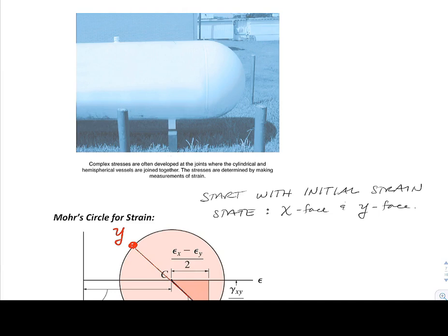And so here's a pressure vessel picture, and really what happens is you end up with calculations that are very challenging to do with a state of stress example. Obviously, we use St. Venant's principle in all our calculations, so we stay away from the area of applied loads and connections. And so to be able to help you calculate states of stress that would be in areas close to supports, close to applied loads, you can use strain gauges.